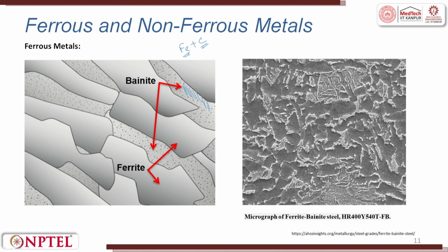Depending upon the microstructure, the hardness value and ductility response change. Just by taking it to different temperatures and playing with time, you try to get microstructures of different types. Though the starting material is the same, you can get 2 different microstructures. These 2 different microstructures signify that their mechanical properties are different.